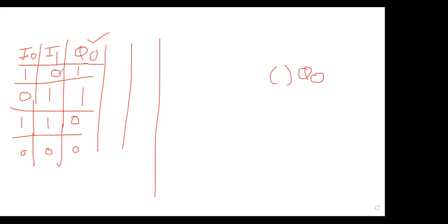And the next example you have to make. Next, 2 more examples we shall make. Look at this screen. I'm going to follow each and every step. First step, make a truth table, I have made. Go to the second step, go to the first output, take a coil for it, I have taken. Now next, you concentrate here, you are confused. See this. Check the true condition of the output. I'm going to check here. Here it is true. Check the true condition of the output and add the status of all inputs you have taken. How many inputs do we have? 2 inputs. So all inputs we have to include.